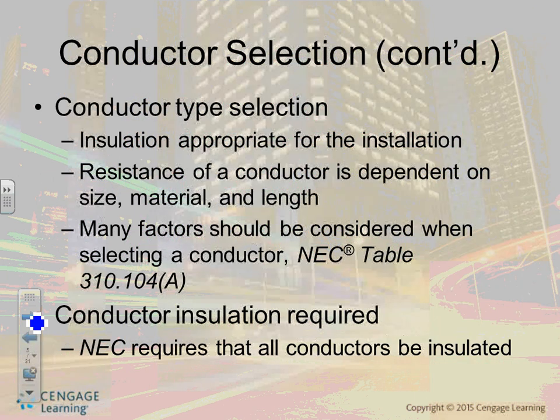You said it's no more than 3% voltage drop. Yes, 3 on what? Feeders, 2 on branch circuits. Why 3 on feeders? They're longer. Feeders tend to be longer. Now, when you size a conductor, we talked about this one, guys, before.